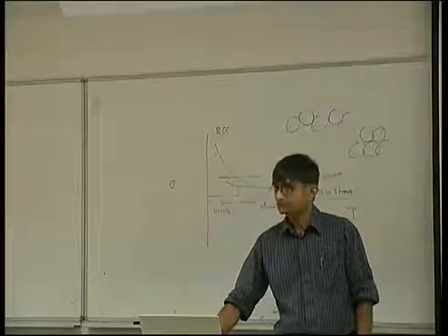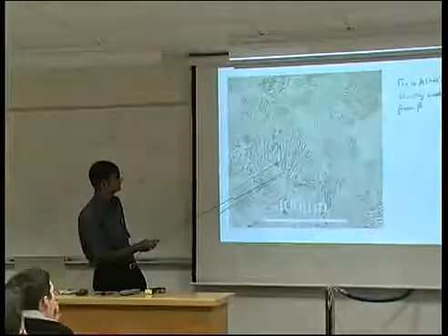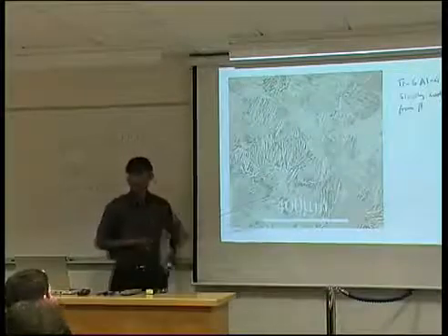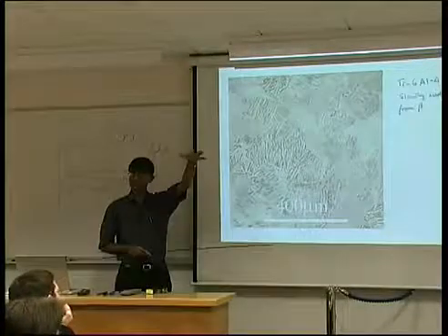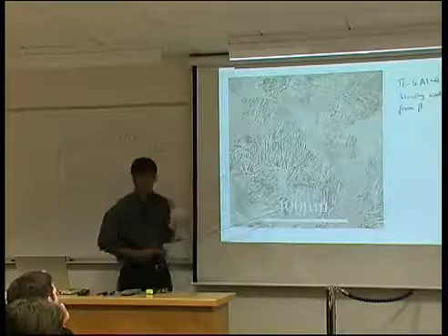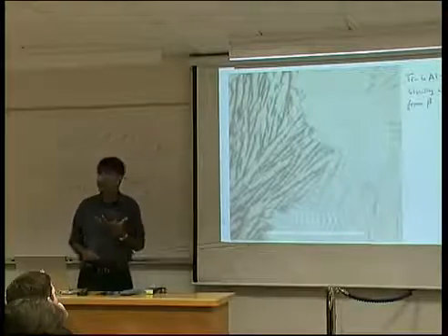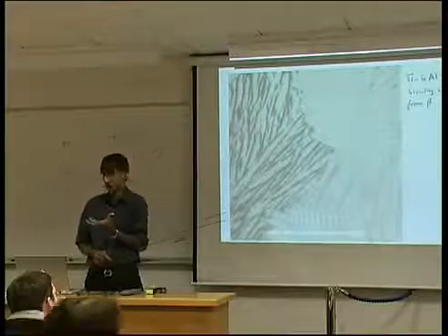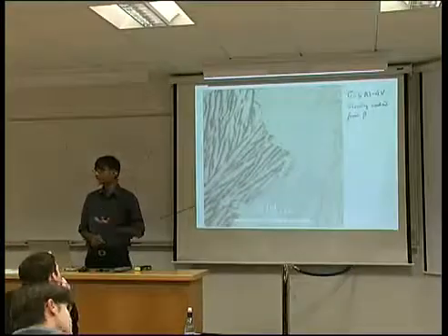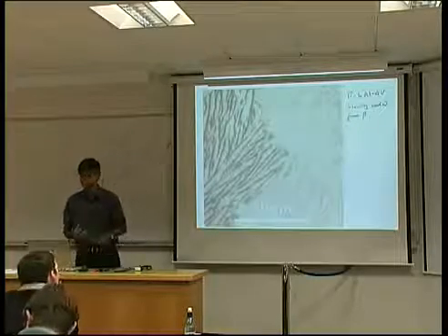Okay, I'll move on. So this is the typical microstructure of a Ti64 alloy, a mixture of alpha and beta. Beta is the stable phase at high temperature, and when you cool it, you precipitate these plates of alpha, and this is a higher magnification image. So you can see where it gets its strength from. It's a very fine microstructure, a mixture of two phases, and therefore the strength is of the order of 1100 megapascals. Very, very nice alloy.